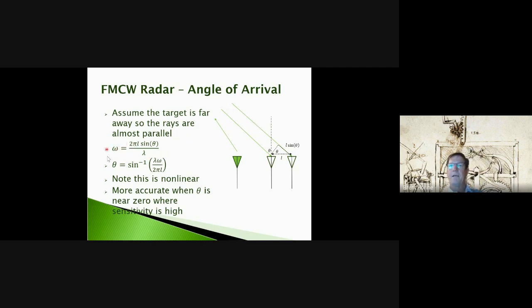Now, with a little bit of manipulation here, again the same concept where the phase of these signals is related to the fraction of a wavelength that we're traveling, okay? And that fractional distance is L sine theta, but it's normalized to a wavelength because we're looking at fractions of wavelength and scaling it by 2 pi radians, right?